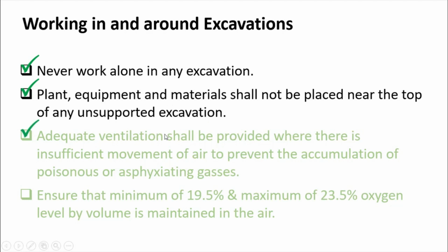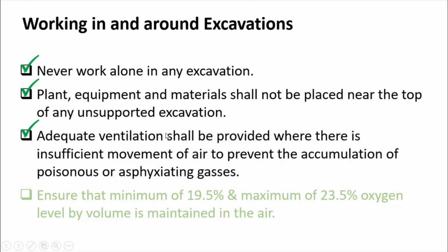Otherwise, don't do it. Adequate ventilation shall be provided where there is insufficient movement of air, to prevent the accumulation of poisonous or asphyxiating gases. So you need to provide ventilation to make sure that there is sufficient breathable air inside the excavations.